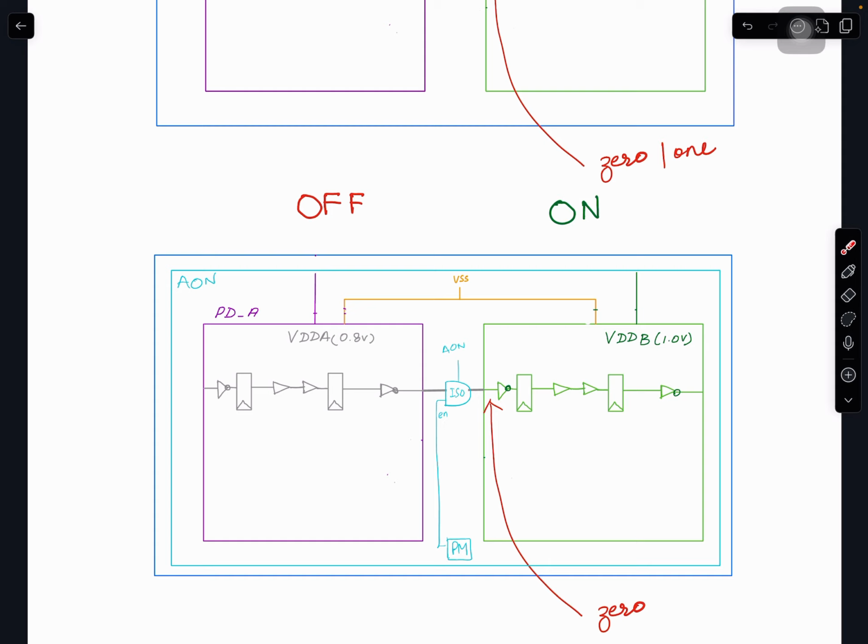Okay, on the timing flow side, you will have these isolation cells in the actual standard cells. These are special standard cells, just like level shifters, which are part of your standard cell library. They will be in the netlist, and when you read the netlist and link, they will be connected to the relevant standard cell in the library.